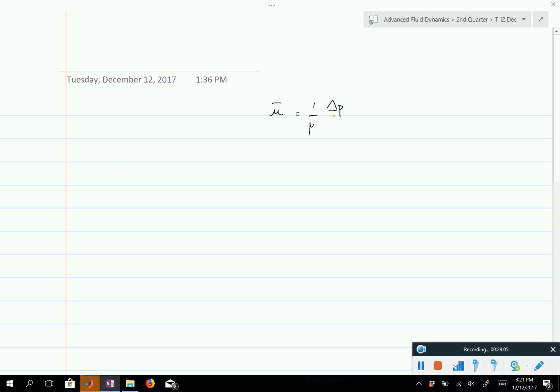And the last thing I need is this delta P. We know from the equation that really it is not delta P which is important, but it's the gradient which is important. So what's going to be important is delta P divided by L. So then you know that U is going to scale with 1 over mu, delta P divided by L, and now you need to look at your dimensions. I'm a bit rushed, so you will see that this number here actually scales with a length scale to the -2. So to finally get a dimensionless number, we need a D squared here.